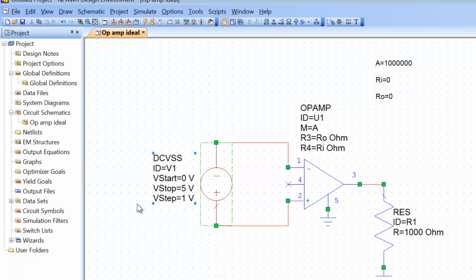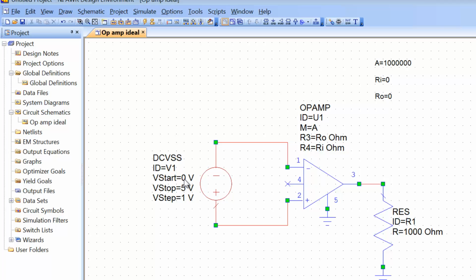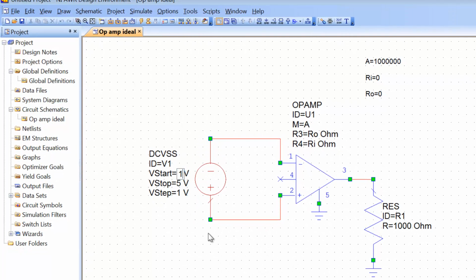Now I can again set a start, a stop and a step for my voltage sweep. So for the start, we'll use the same as we used before, 1e-6, which is 1 microvolt. For the stop, we will use 1e-3, which is 1 millivolt. And also we'll have an identical step to our tuning range, which is 1 microvolt.